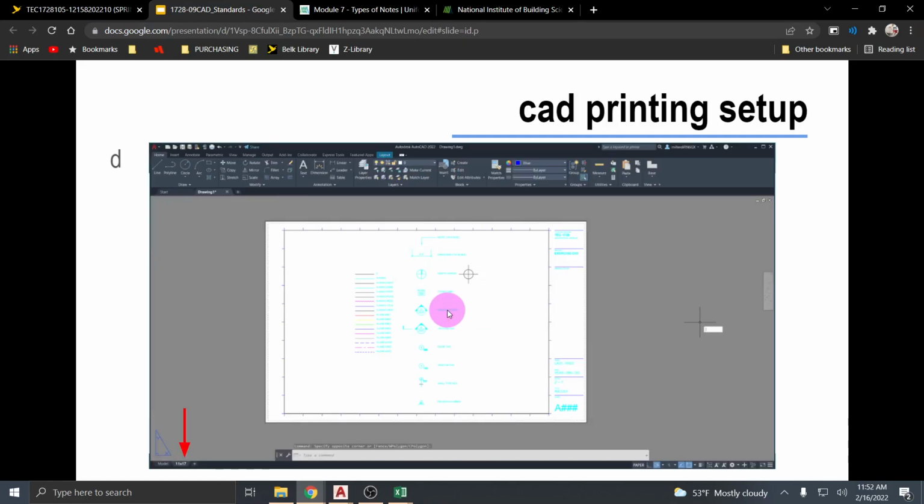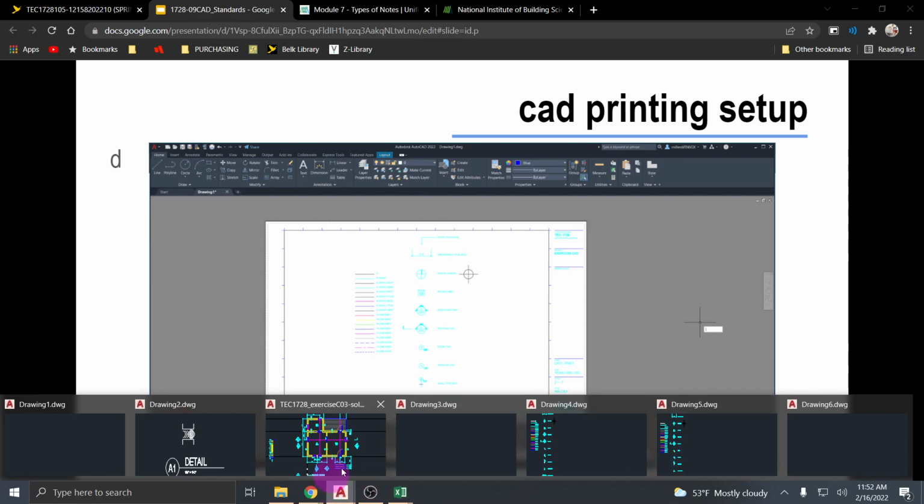And then lastly, for how the standards can work in AutoCAD, we can also set objects up to print. So we can set up our different page sizes and our different title blocks and have that all preset in template files to print our drawings out easily, zoom in on different areas, set them to scale, and then have our different line types print with different line weights. So based on the color of the line in AutoCAD, it'll print either thicker or thinner on paper.